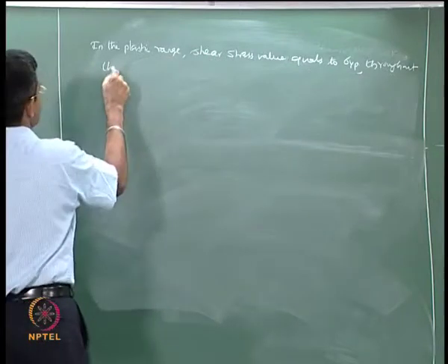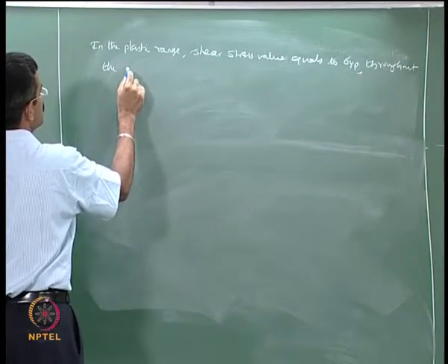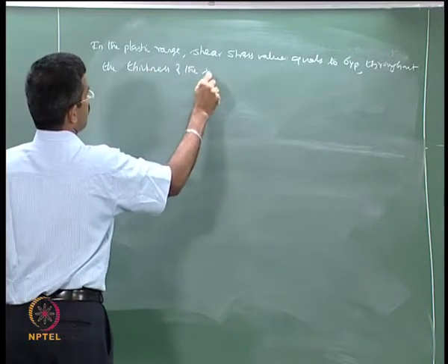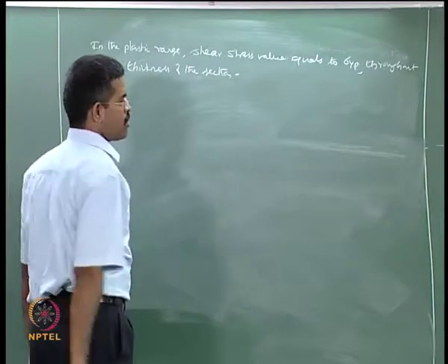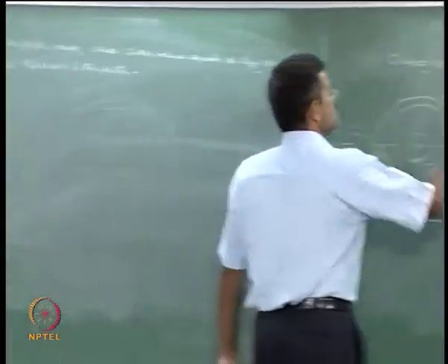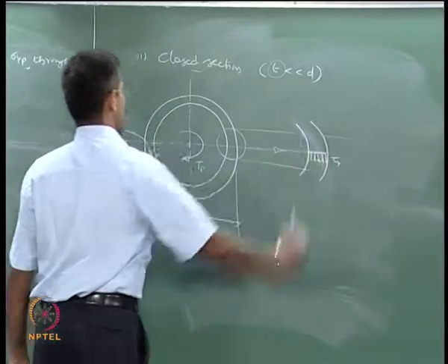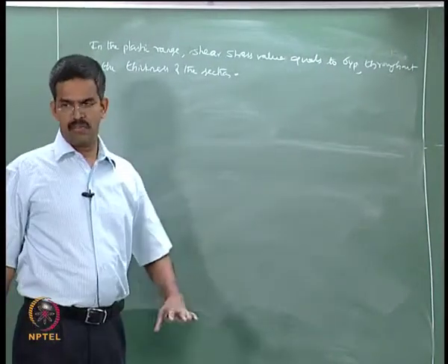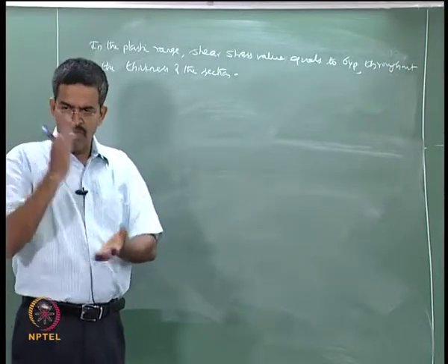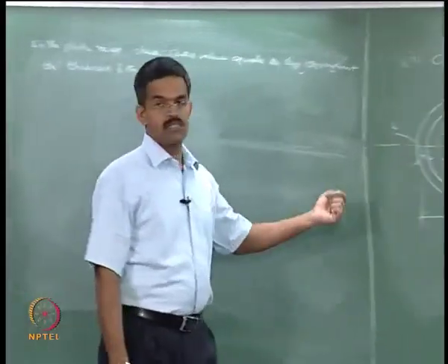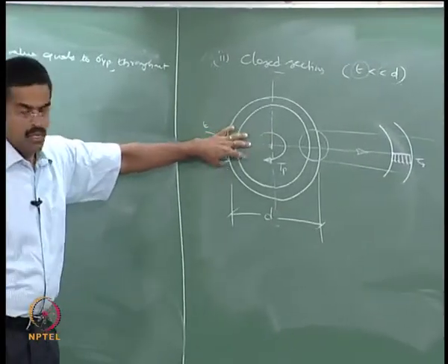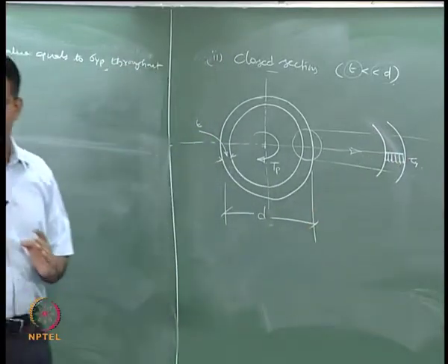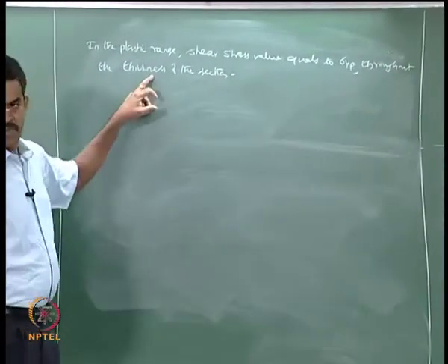That is an assumption or reality. This is true because we are talking about the thickness being very small compared to the diameter of the section, a thin walled section. So the thickness is uniformly plasticized for the whole value of T. There is no question of a partial plastic and partial elastic core lying within the thickness, okay. It is fully plasticized, the full thickness is having tau y, okay, that is the statement.